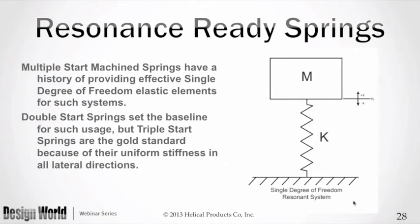This picture that's on the right is one that probably everybody recognizes, everybody who's been through some formal vibrations training. It's a single degree of freedom system with a mass and a spring. When we saw these, we just assumed that, yep, there's the mass, there's the spring, and yep, it's a single degree of freedom system, so it made it easier to analyze, and away we went. Little did we know that spring didn't exist, at least when these first diagrams were made. A wire-wound single-started spring, which is typical wire-wound, and a wire-wound even machine spring will not work in that system. There will be that moment that I was talking about earlier in existence there.